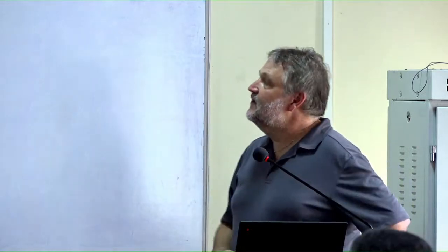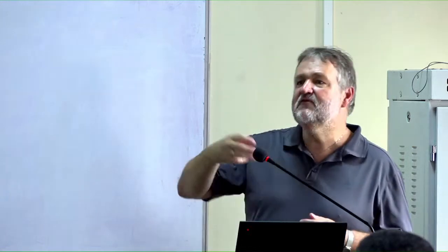Yeah, Andreas is not only wearing strange hair, but he's doing research about particle dampers. If you want to reduce vibrations, you can use tuned mass dampers, which are very nice, but with tuned mass dampers you damp only a certain frequency. If you know you have a problem with, for example, 50 Hertz, then you can make a nice tuned mass damper, removing most of the vibrations at 50 Hertz. The 50 Hertz in Germany is a little bit infamous because a lot of electricity runs at 50 or 60 Hertz, and so some of the excitation from electric motors is in this range. So when we see 50, 60 Hertz, we always think, no, this is electrical engineering.